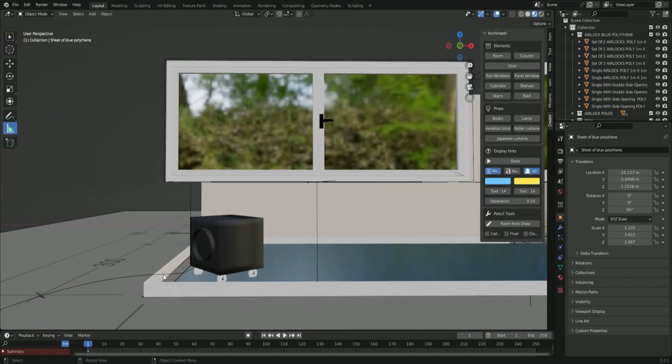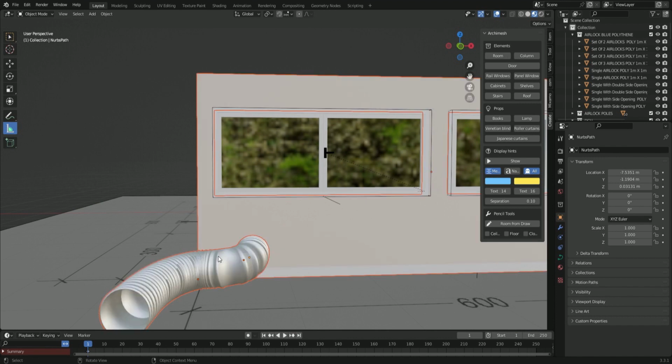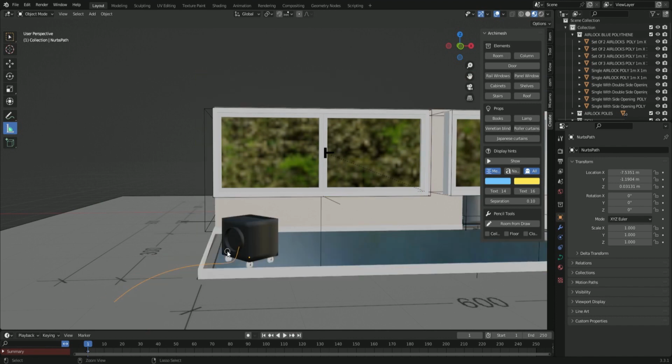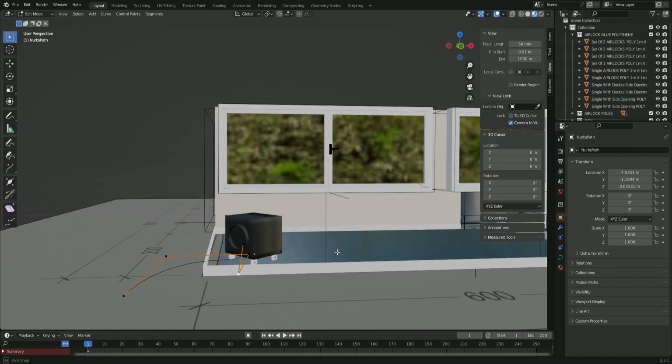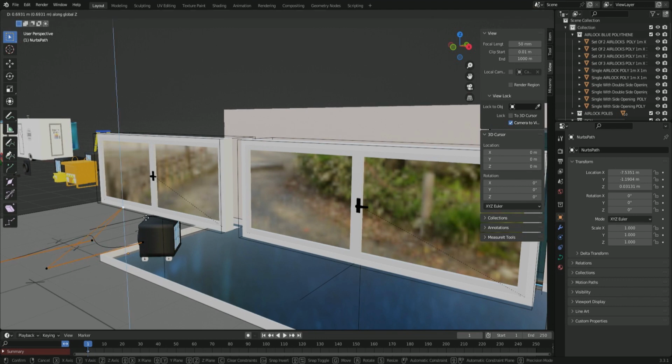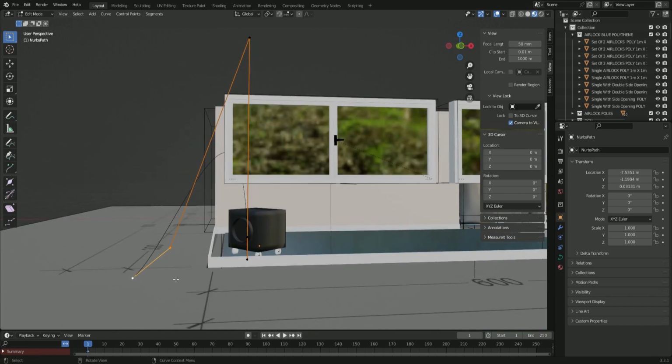It has a modifier in it. On the right, as you can see, there's a spanner. Within that, it has an active modifier array, and it follows a curve. So if you alter the curve, and the curve gets quite long, then you just up the count on the array. I'll show you in a moment.